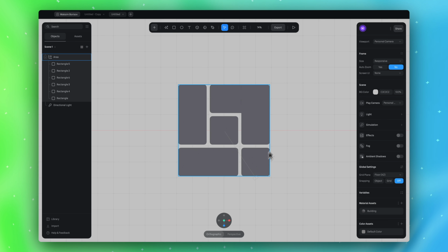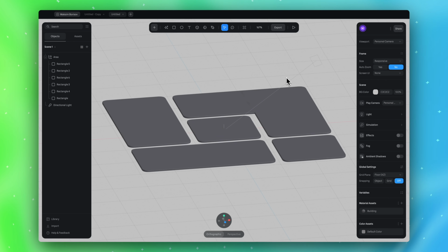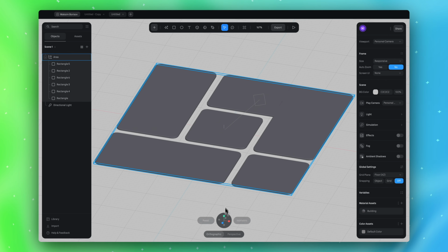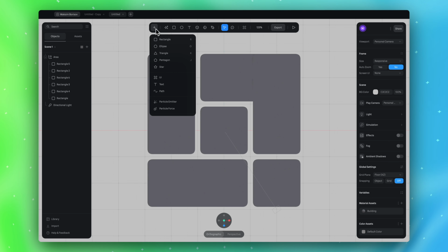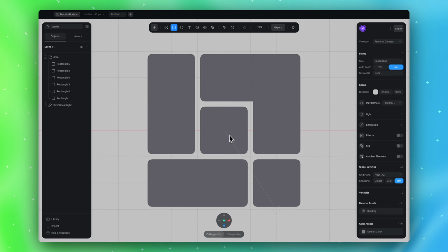Okay dokie. Now, because this is area, which means it's like a pedestrian area or something like that, we see this space between these areas, which would be like our road. To add road, we can also use a rectangle, or we can use plane. Remember that you cannot extrude plane. You can only transform plane to mesh object, and then you can extrude, but it will be hard to manage. Better to use rectangle in that case, because rectangle you can extrude.